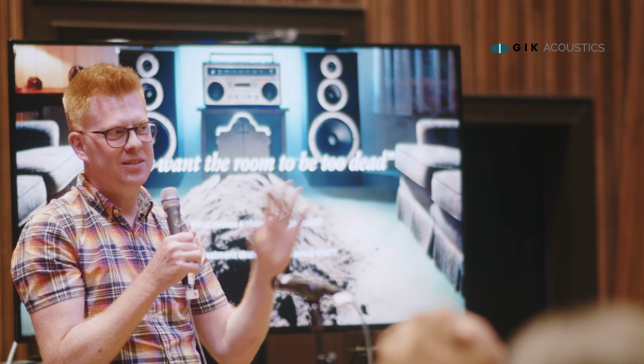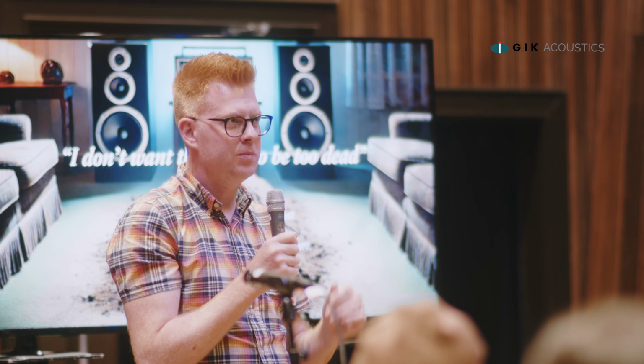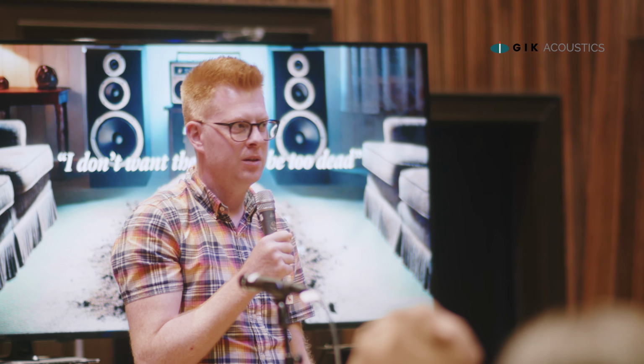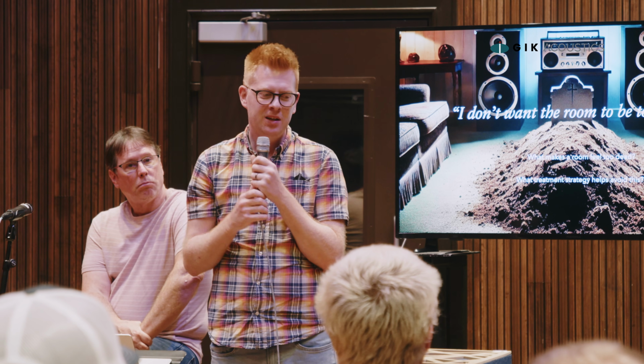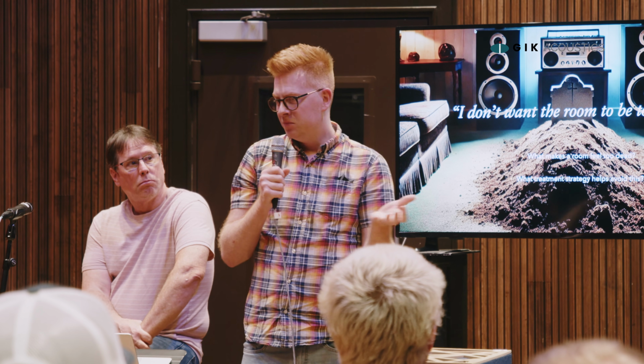If you have a room and you just put up a load of 1-inch pyramid foam and cover all of the surfaces, all the first reflections, the highs and mids, maybe the higher side of the mids, are going to be dealt with pretty efficiently. But the only problem with that is it's kind of like turning the bass control up on your hi-fi. Now you have an overemphasized bass, and you have even more of a muddy, boxy room than you did to begin with. And if you're using foam, then it might catch on fire as well.